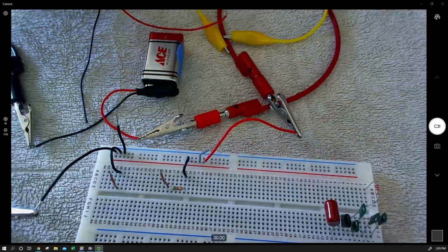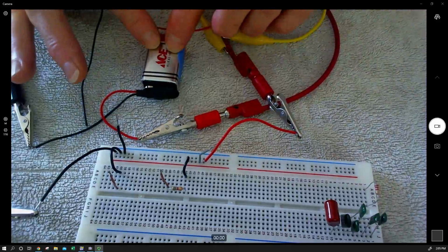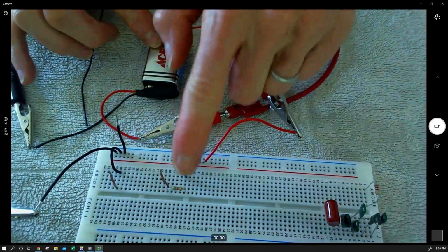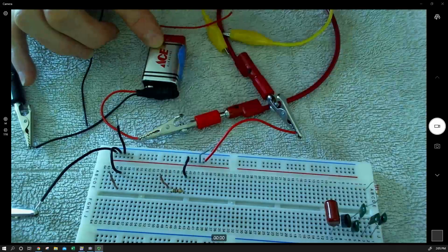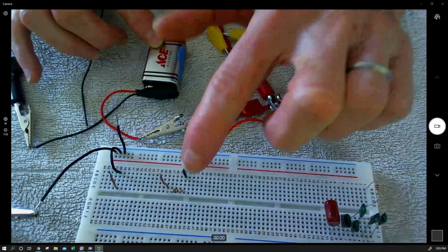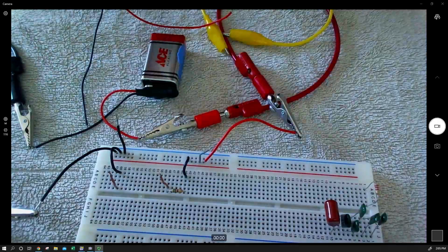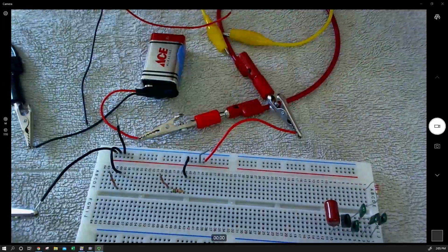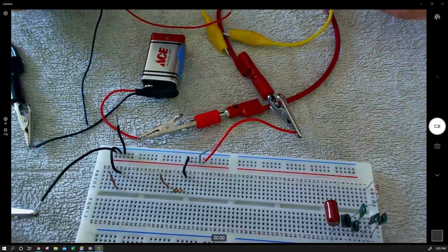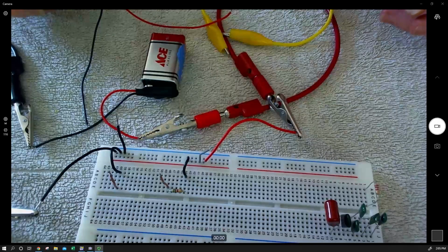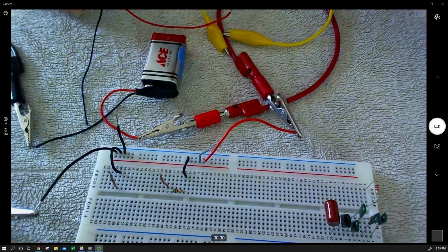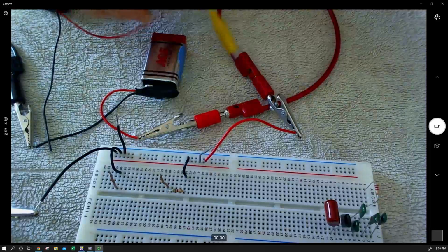So what that is telling me is that in spite of the fact that I have fairly substantial internal resistance in this battery, it's nothing compared to the impedance provided by my load circuit. So my load is effectively the rate limiting step, or the high resistance point in series for the current. So with this scenario, I could add another source in parallel, and it probably wouldn't change anything because the resistance of the battery is not what's limiting. But let's just hook it up and confirm that.